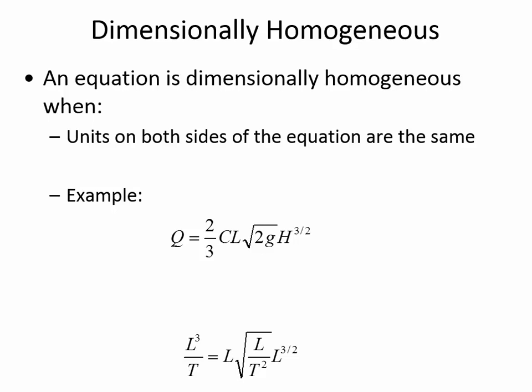And so is an inch acre per hour the same as a cubic foot per second? It's not the same. Actually, it's close. If you actually do the conversion, you only have to multiply it by 1.008, and then it does turn into cubic feet per second. So most of the time, they just ignore the 1.008, and by coincidence, it works out that inch acres per hour is pretty close to cubic feet per second. So it's not dimensionally homogeneous, strictly speaking, but the units just sort of work out by dumb luck.